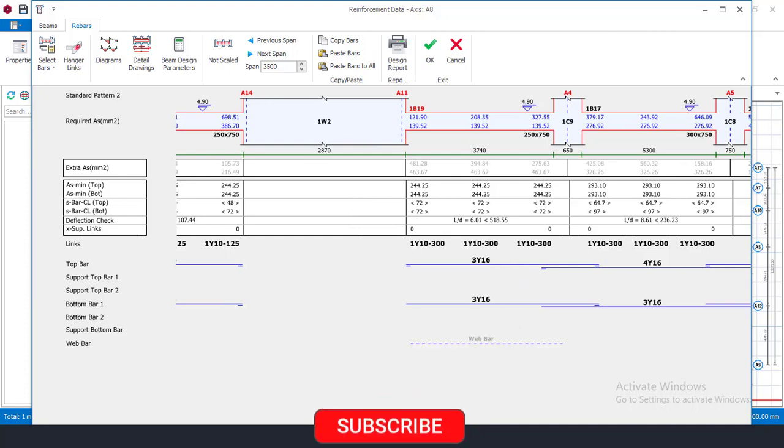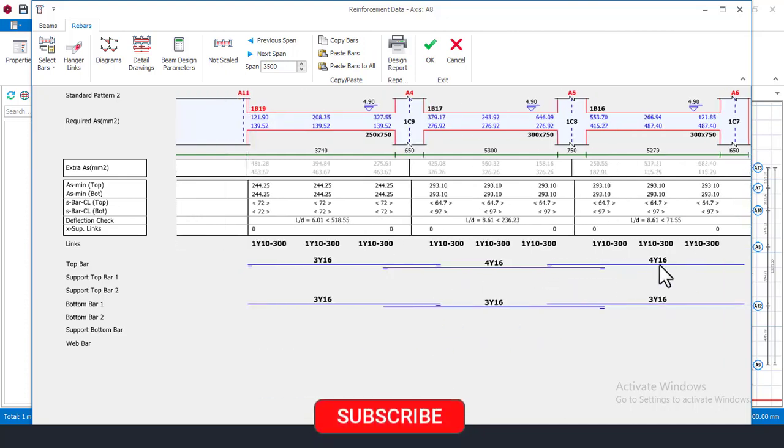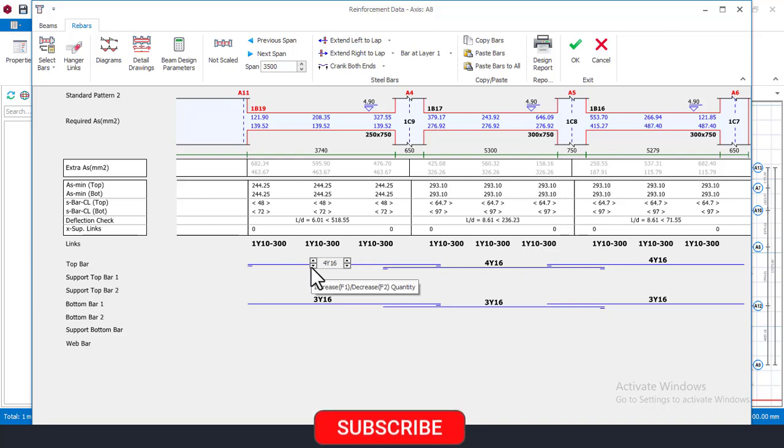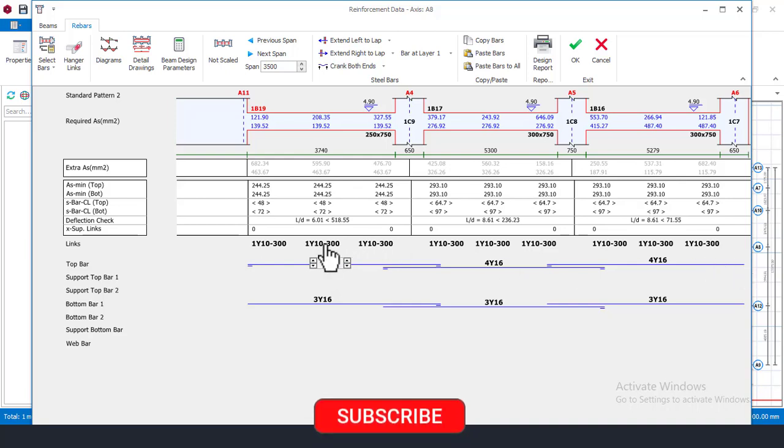So just to have a smooth placement of my reinforcement during the construction, here is giving me 4 number of 16, 4 number of 16, and this one is giving me 3. To have smooth placement of reinforcement during construction, I will make it 4. Basically 3 was okay for that, but just to have a smooth placement, I'll make it 4. I can choose to make it 3, but just to avoid confusion at sites, I make it 4 because this place is very small compared to these other panels here. So just to have a smooth lane of your bars and to avoid much cutting, let me carry the same bar length and flow all the way down here.